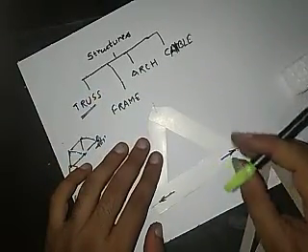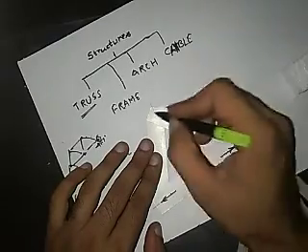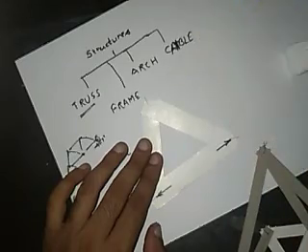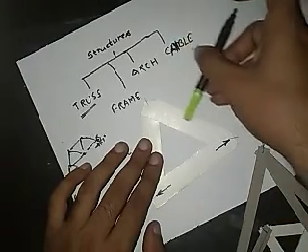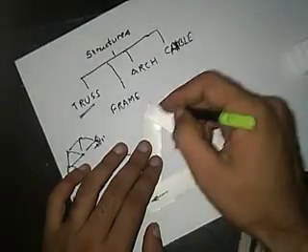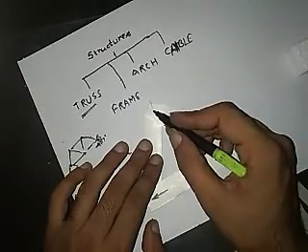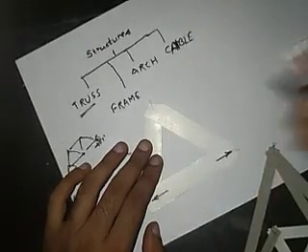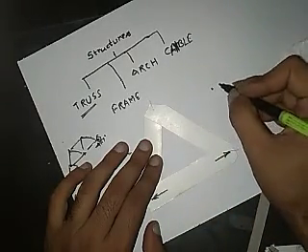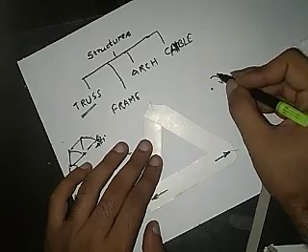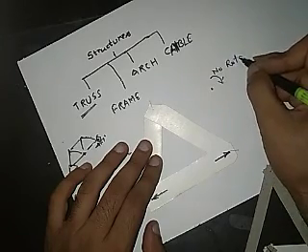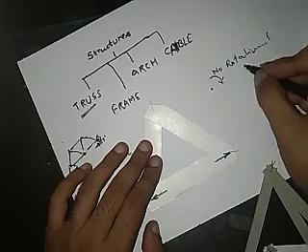Okay, so what are the advantages of these two assumptions? The first assumption, that all forces are transferred through the joints, tells us that there will be no force acting in between those points. And the advantage of these pin joints is that at this joint there will be no rotational resistance.